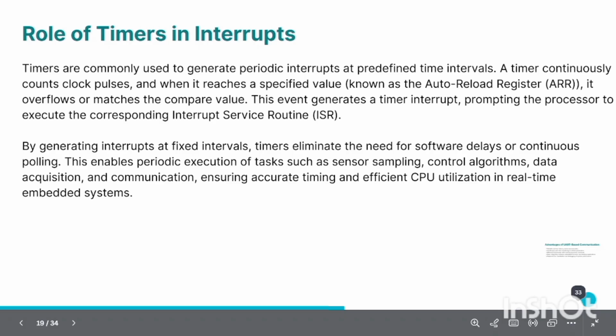Role of timers in interrupts. By pairing hardware timers with the interrupt controller, we generate precise periodic interrupts. When the counter matches the target value in the auto reload register, it overflows and triggers an interrupt. This eliminates the need for software delays, ensuring accurate intervals for sensor sampling and control.